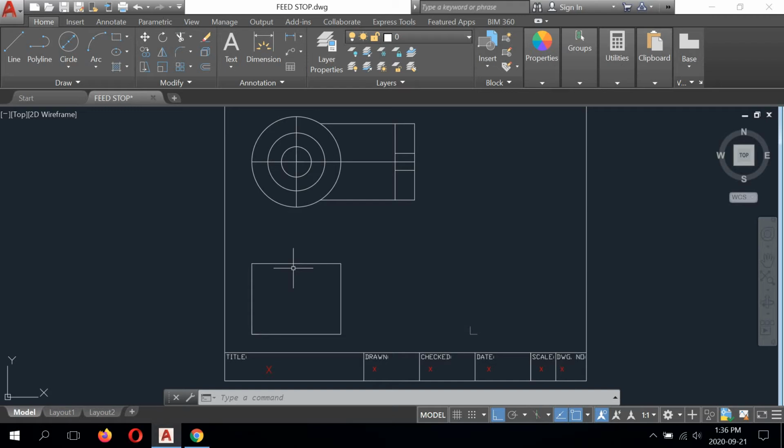Now, we have holes that are passing through the cylinder. So we have to show those. But because we're working in orthographic projection, those details are not going to be normally seen to our eye. So basically, those circles that represent depth, we couldn't see them by looking at this part of the cylinder, but we still have to show them, but we're going to show them as what's called a hidden detail line. So this is something that is practiced in the Drafting Fundamentals module that is done with grid paper and pencil.